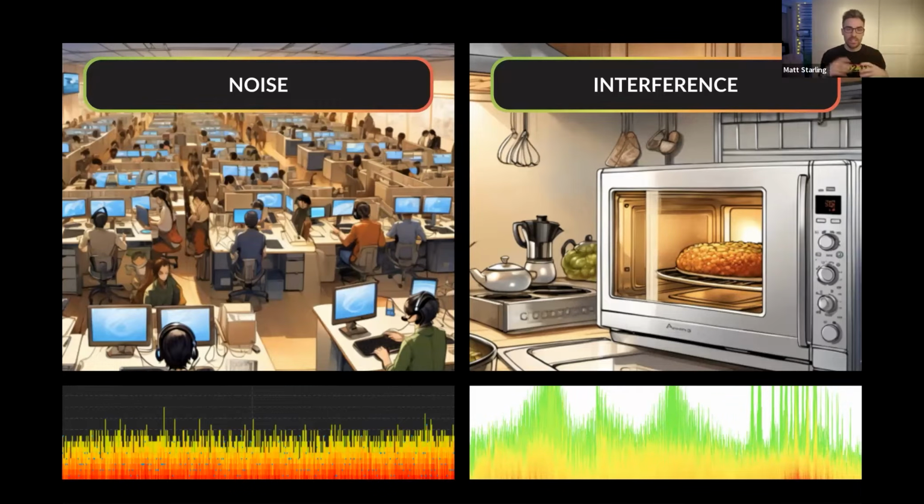All of these different devices in a busy environment are going to raise the noise floor. You remember that background noise that we were just talking about? The more of these devices that you have in the environment, the higher the noise floor is going to be. That means we're going to need a stronger signal strength to be able to achieve higher modulation schemes, and then transmit our data faster, which is what we want.